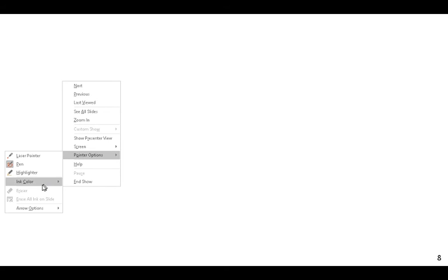But now that we have really thoroughly analyzed bending, let us check this thing for shear. Just as I took the maximum location along the beam for bending and the maximum location in the cross section for bending stress, I'm going to do the same for shear.